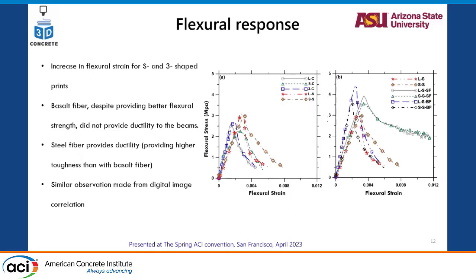So this is the flexure strength response that we got for the beams. I think it was discussed in yesterday's committee too that we can't get this post-peak response in beams, usually non-fiber beams. And it was the same case. This is a representative figure among the 6-7 beams that we tested. 1-2 showed us post-peak response while most did not.